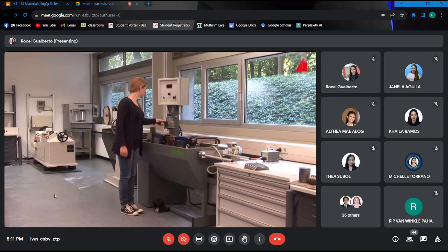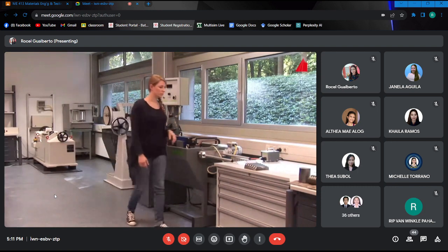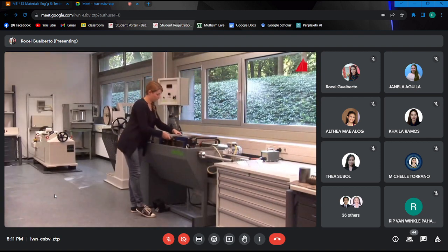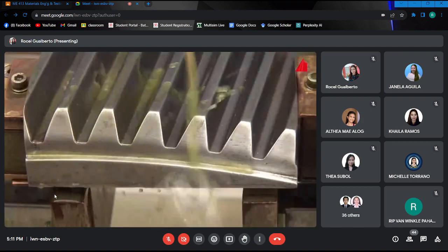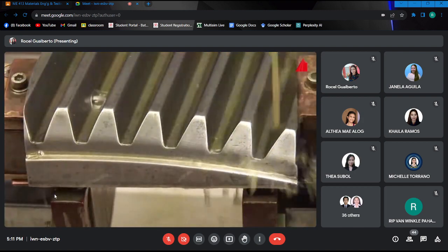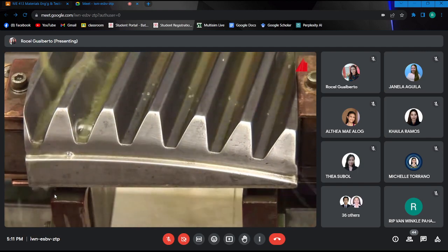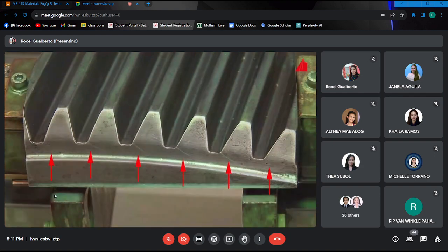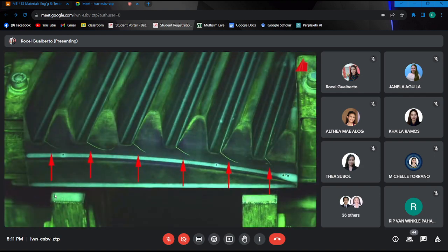Still, another test piece has to face the magnetic particle inspection, a section of a large gear wheel. The same procedure again. Placing the gear wheel between the magnetic pole pieces, magnetizing and applying magnetic particle suspension. Already in daylight, there are indications of cracks, and again, they are best visible under ultraviolet light while darkening the daylight. The visible cracks are so-called fatigue cracks. They have been generated during the operation of the gear drive due to a mismatch of the gear wheels.